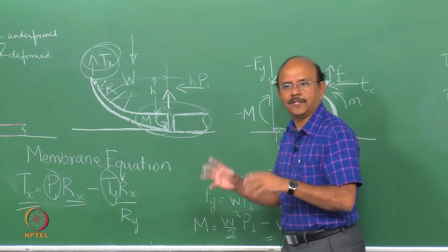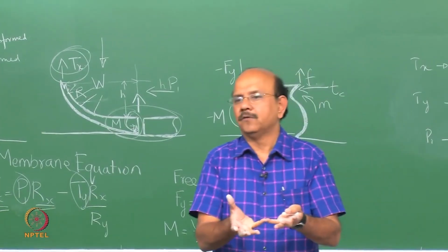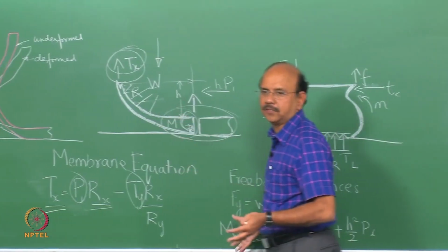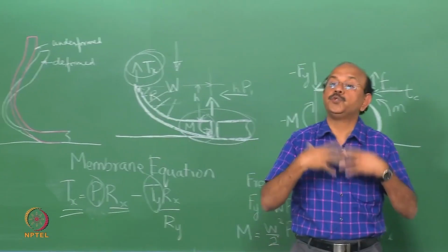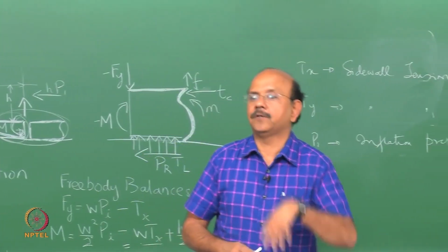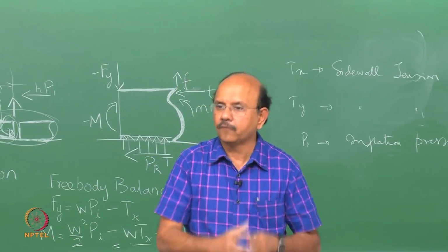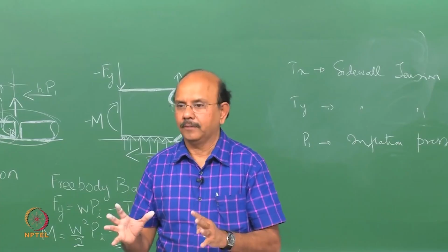That's the reason why we explain what is bending, how does it bend, what are the forces which cause bending. We can't do hand waving. That's why we write down these equations and see, look, there's a moment, and the moment is due to various forces, and forces act because of inflation pressure, because of the force of the membrane or the sidewall forces. These participate in this moment and so on.